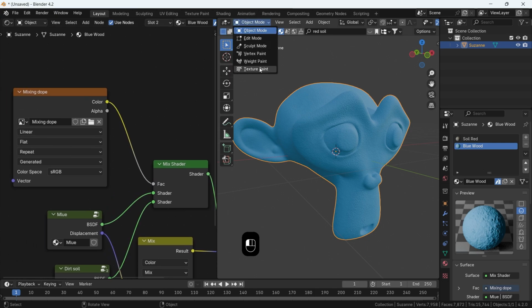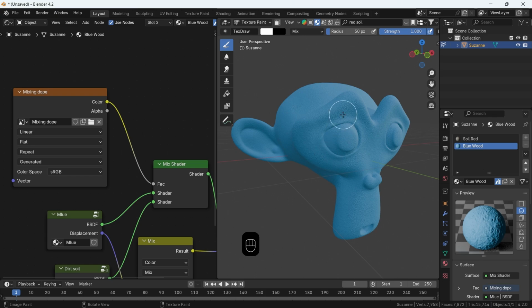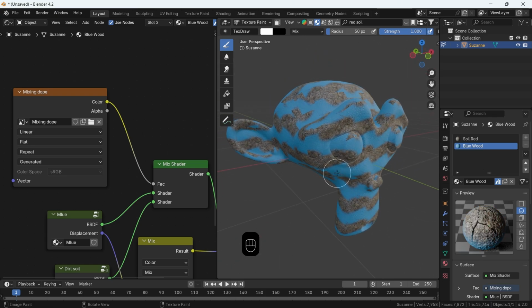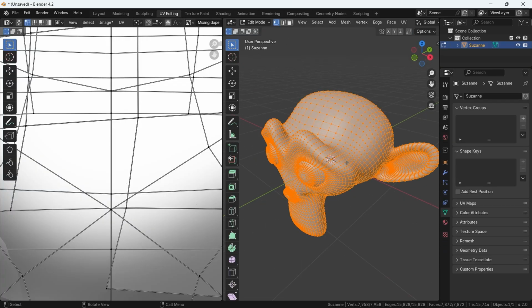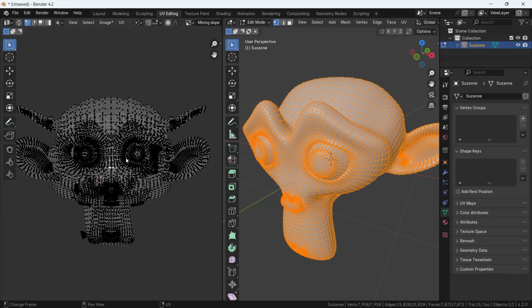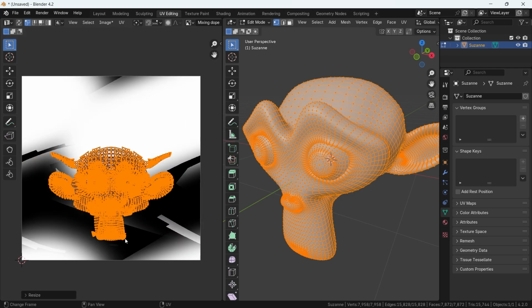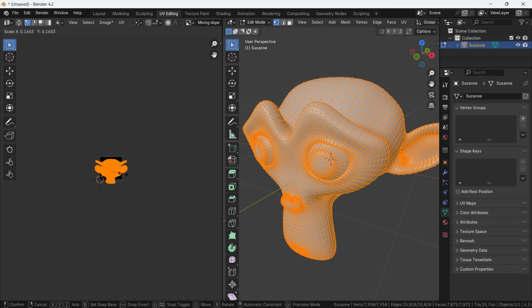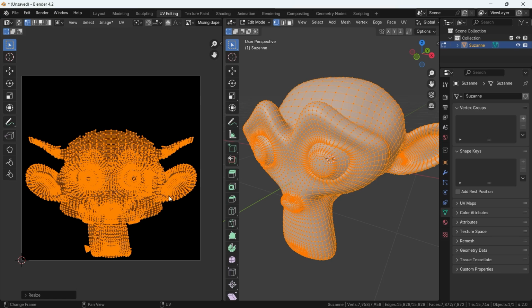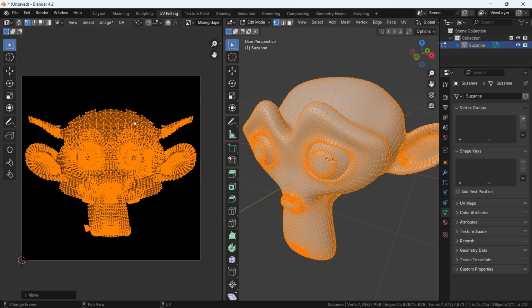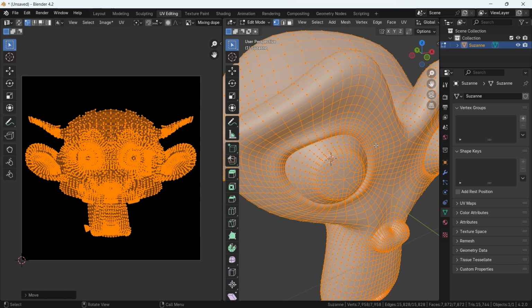Switch to texture paint and try to draw on it. Something will happen, but it's a mess. That's because the UV in this shape is not suitable for painting. See, if we go to the UV editor, the monkey unwrapping is way bigger than the texture size, and there's some of the paint we did, so maybe we go back a bit to make it blank again. Then we can scale down the UV to the map size to fix it.